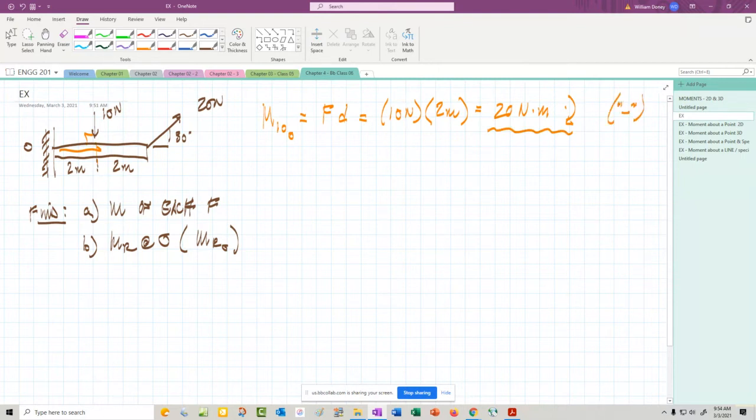Again, we typically view counterclockwise as positive. I'm not sure exactly why that is. It's just the way that I was taught also. I think it's that if we have this beam, let's say it's a deck, if it rotated clockwise about the hinge and failed downwards, that would be bad. And so we take that as negative. That's kind of how I think of it. So if the moment is positive, meaning it's counterclockwise, that means we're holding this thing up.